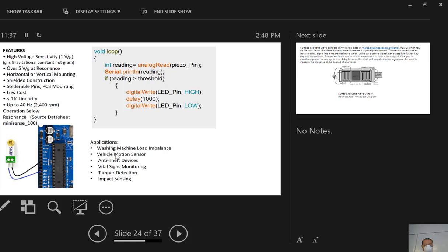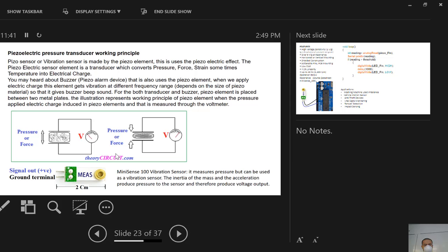So we're now going to look at piezoelectric material, which you probably want to know about. It's another type of pressure sensor. The pressure will generate the voltage. With this type of material, when you give it a pressure, charges directly accumulate on the 2 plates. Very interesting. You still have to amplify it. It's called a piezoelectric transducer.